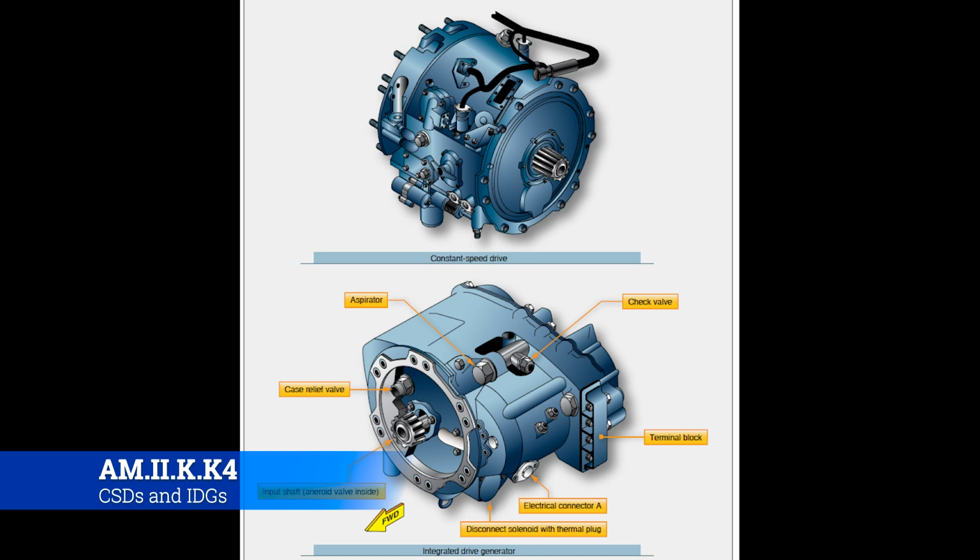Now, the CSD can be an independent unit, or it can be mounted within the alternator housing. And when the CSD and the alternator are contained in the same unit, the assembly is known as the integrated drive generator, or the IDG.